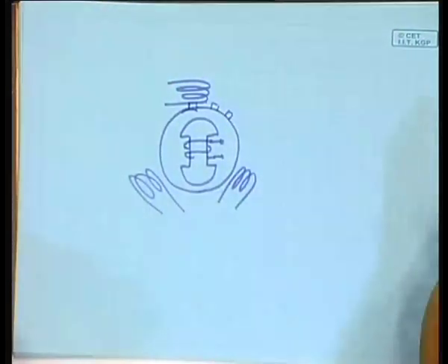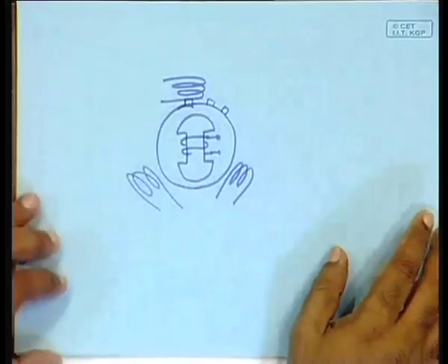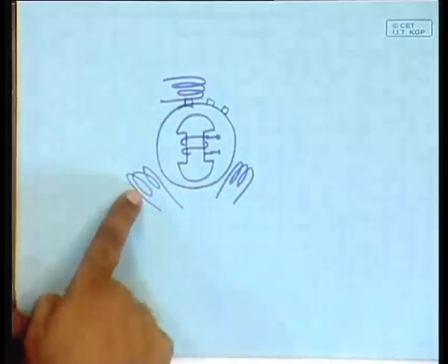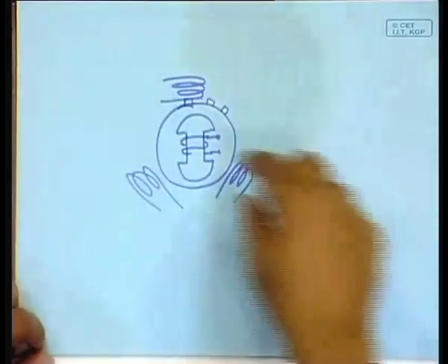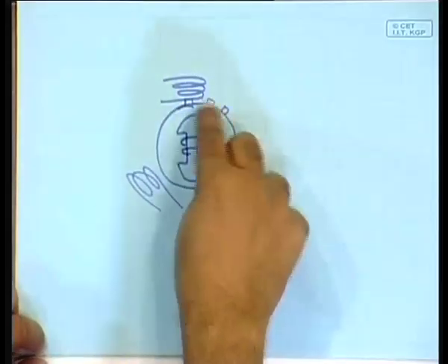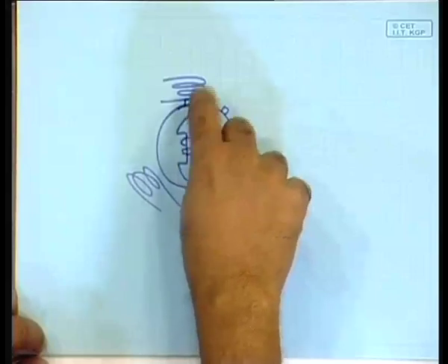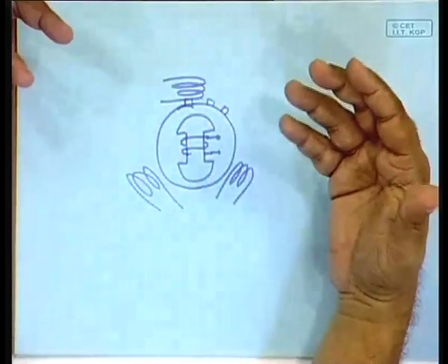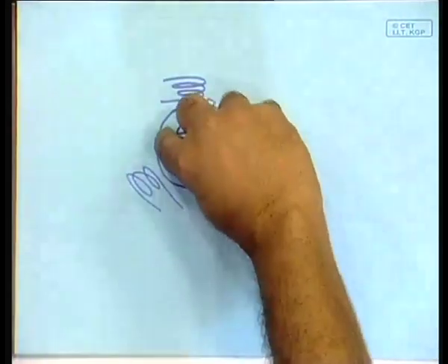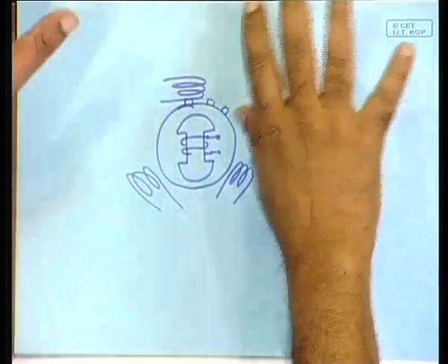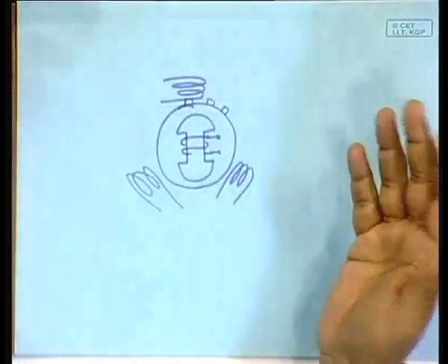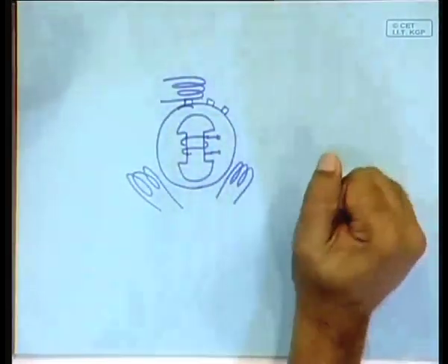Now, the speciality of this machine is that the voltage that will be generated in each of these, they will be sinusoidal. Why? Because the north pole is rotating and it is passing by, while it is just under this, then it has the largest rate of change of flux. As a result, it will produce, and then when it comes in between, then it sees the least. So, the whole thing will vary sinusoidally, and after some time the south pole goes there and does the same thing. So, you will see a sinusoidal voltage generated.